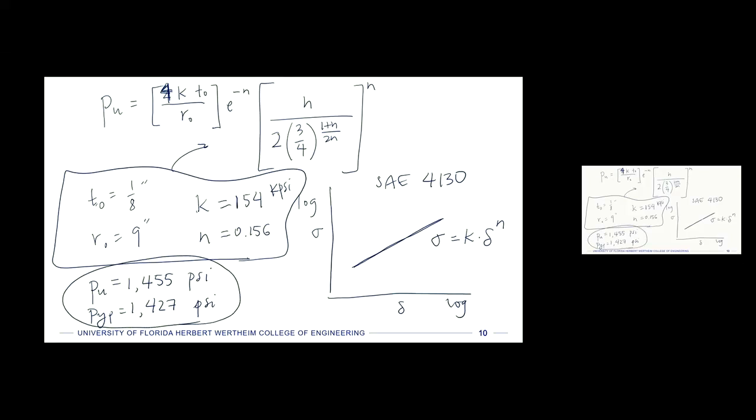So this is a really helpful guideline, right? Okay, maybe we do get a yield. Well, what if we have an issue and the pressure inside this pressure vessel keeps increasing? Well, if it gets up to about 27 psi higher, then it's going to have a plastic instability, plastic collapse, the pressure vessel will burst.